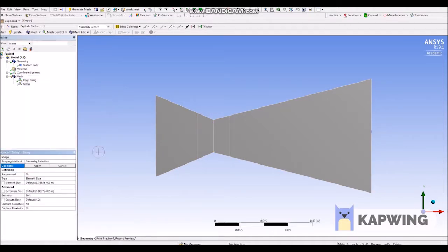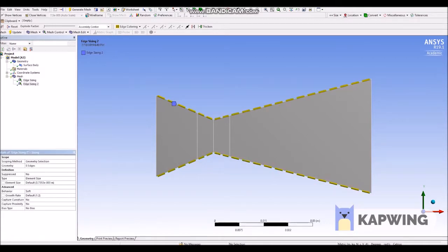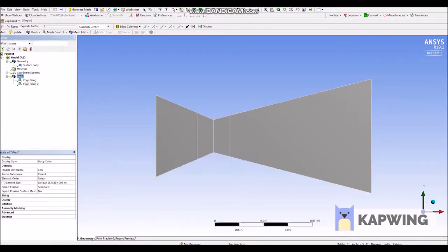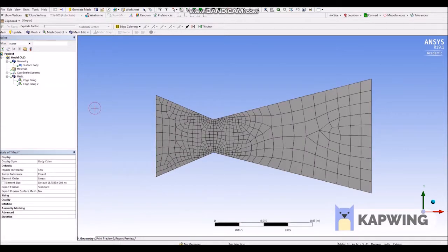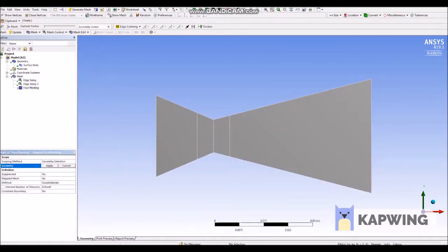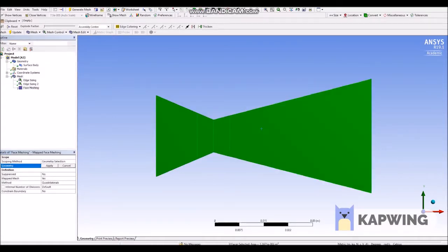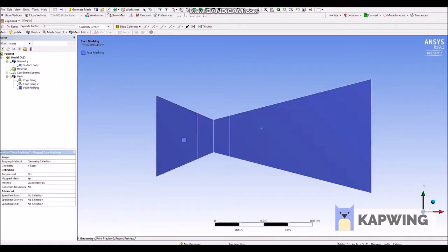I will make it 10 divisions, and also make it for the wall lines, the same number of divisions, 10 as a start for mesh 1, to see how the result will behave after making different meshing. Now we have to generate, and as you can see the mesh is unstructured. And now my colleague Soroush will continue speaking about it.